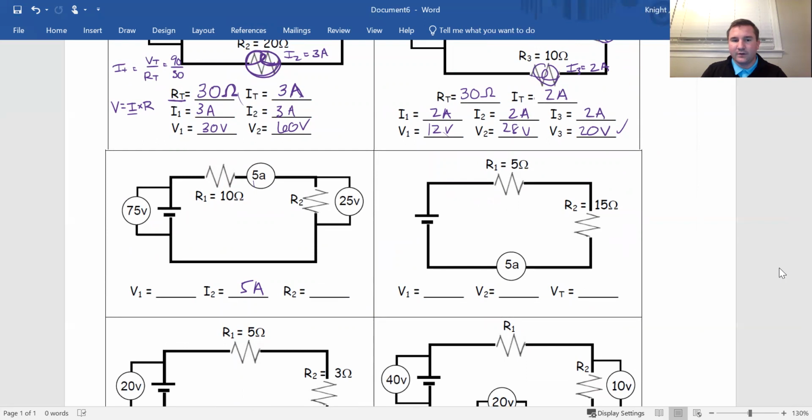These ones are a little bit trickier to figure out, but we'll puzzle through it. I want to know the voltage over 1. What's the voltage over 1? So there's actually 2 ways to do this. First, we know the current is 5, right? We can see current right there. We can see resistance. 5 times 10, 50, right? That's Ohm's law. V is equal to I times R. If the current is 5 here, then the current here, I1 equals 5, right? I2 equals 5. Current's 5 everywhere. So 5 times 10 equals 50. That'll give us the voltage.